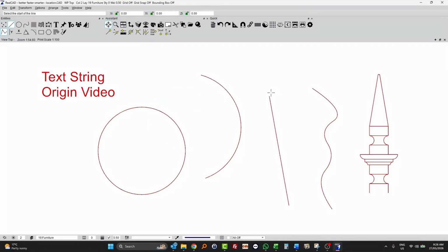The same is true sometimes for lines. The origin of a line is at its center. And yes, you can work your way down until your cursor changes, as it does here, and now I know I've found the origin of this line. Terrific. There is no origin for a curve because a curve bends in so many different directions, so there is no actual origin. And for an object out of a library, the origin is only its insertion point, which is not always that useful either.